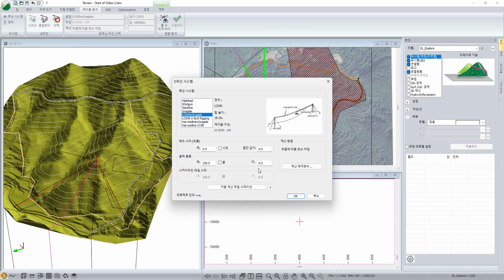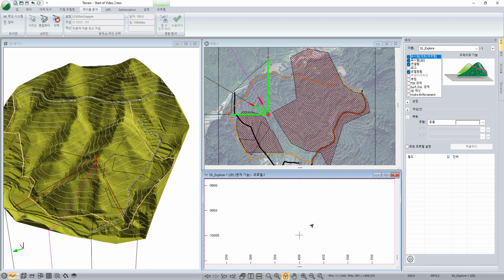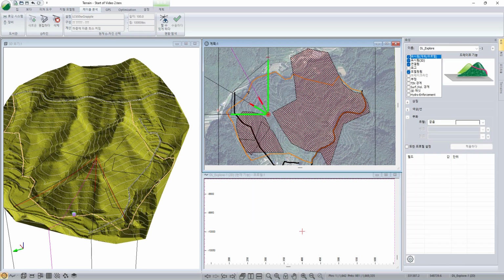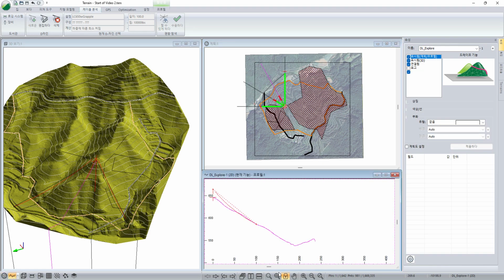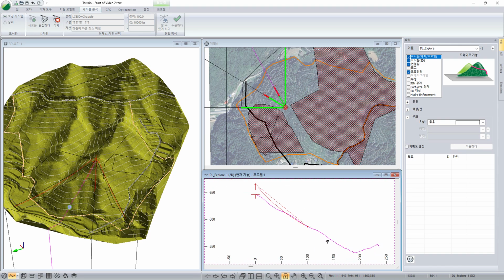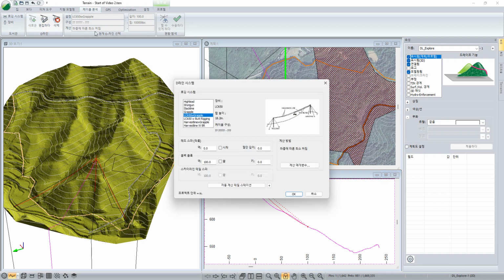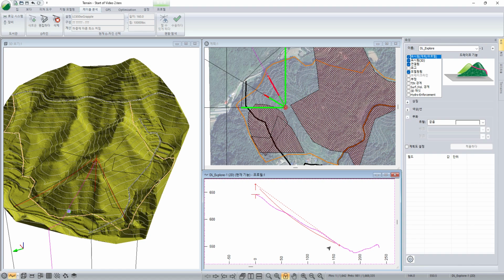Similarly here, we could check that out, and here we're going to have deflection issues too. Oops. I'm just going to click zoom to extents so we can see that. So again, we've got deflection issues, and if we push this out further, say maybe to 160, it's going to be even harder to get the lift that we'd like.